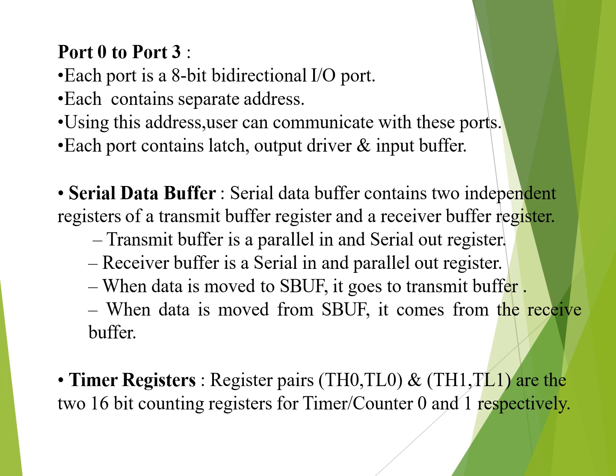The next register is receiver buffer, which is a serial in and parallel out register. So this register is used to receive the data from the peripherals. So the peripheral devices will generate data serially that will get collected in the receive buffer. It will get converted into parallel data, and after that it will be given out to the microprocessor. So that is what it is named as serial in and parallel out register.